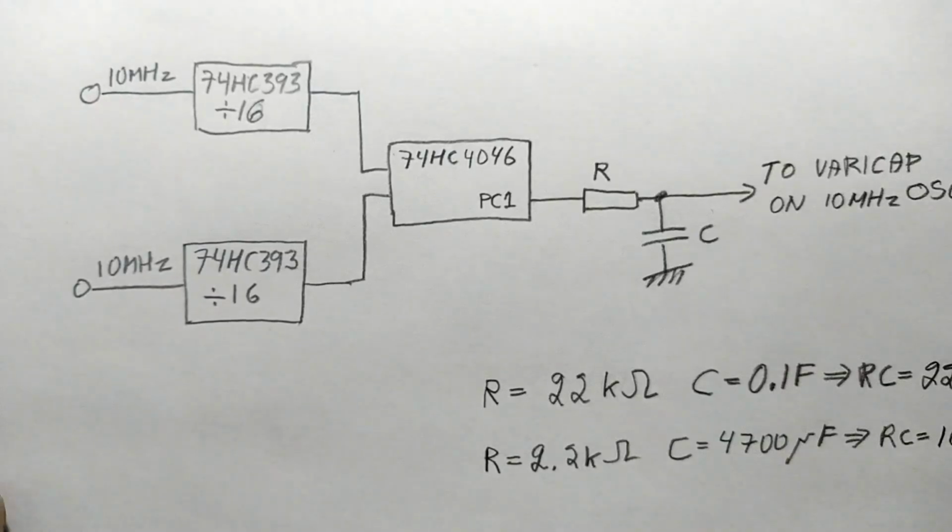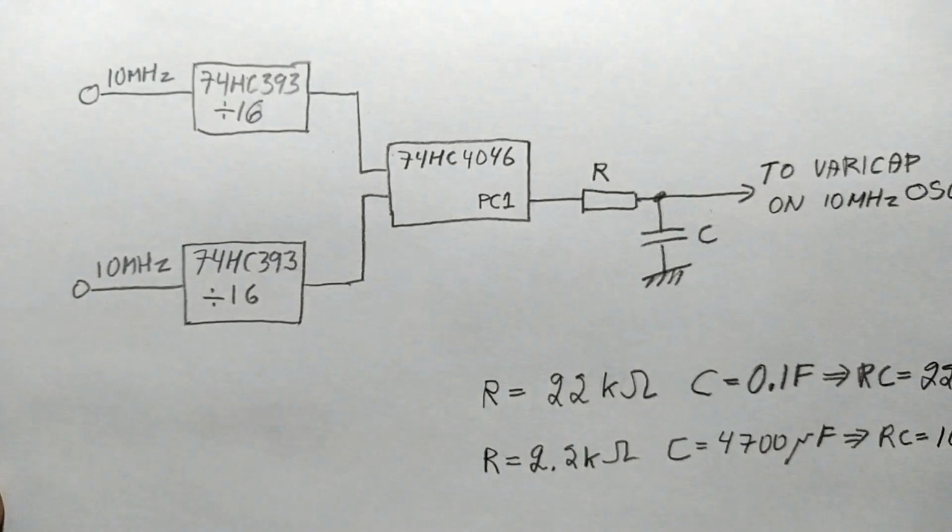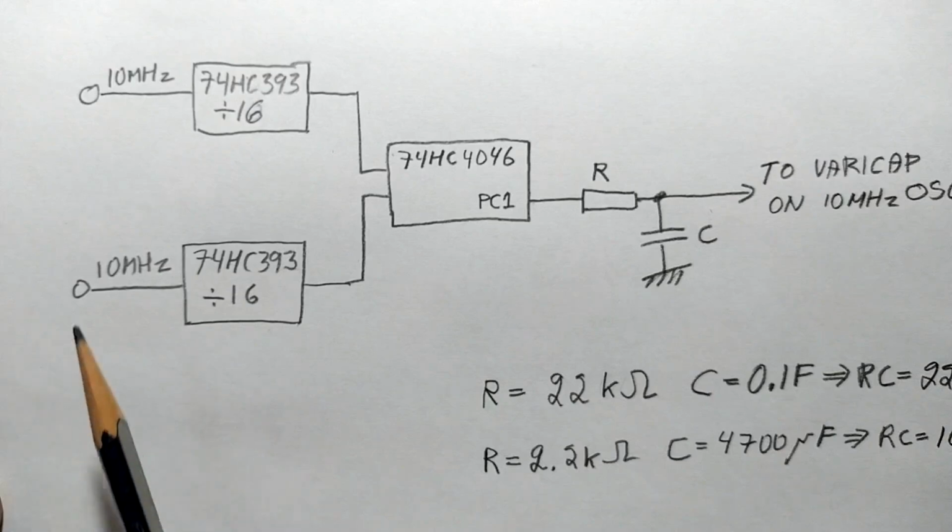I have started to use a rubidium stabilized oscillator to lock both reference oscillators to the same frequency. So I have built now two new phase lock circuits like this.